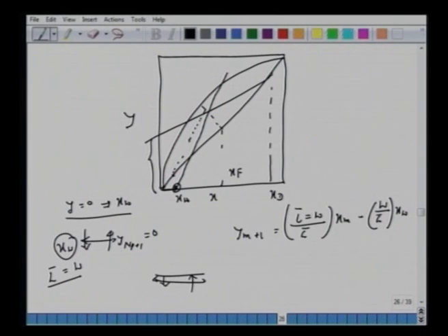So for the bottom tray, we have y np equal to 0 because it's pure steam, and xw is the bottom product composition, which is known to us. We mark the point here, and now we connect to obtain this intersection. So these would be the two new operating lines. Remember again, instead of starting from here, we have to start from here, because earlier xw also yw satisfied this operating line equation. Now y equal to 0 and xw satisfy this equation. So we have modified this McCabe-Thiele method.